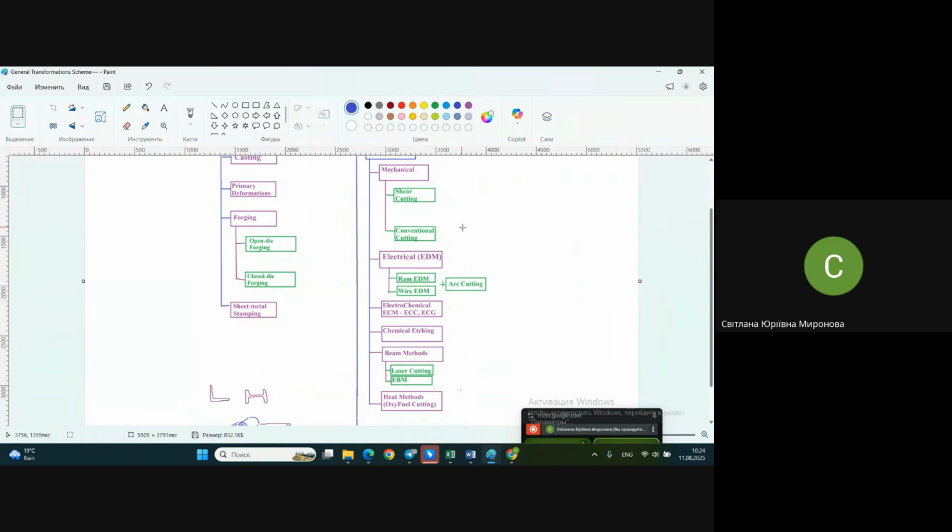Well, once again, look, this conventional cutting. Let's talk about conventional cutting by blades. Just by blades. What does it come to? Turning, when the workpiece rotates and a tool does linear motion. Milling means that you have some blades already. It's multi-blade. No, it's called in English single point cutting for turning, for instance, and multi-point cutting for drilling, milling, and some other techniques. With multi-point cutting, you have some blades in contact with the part, and it's necessary to move them along the path.